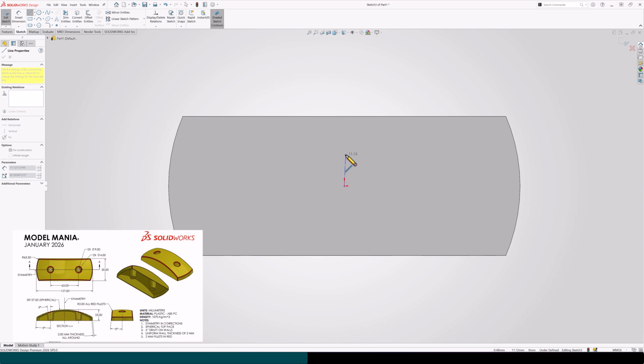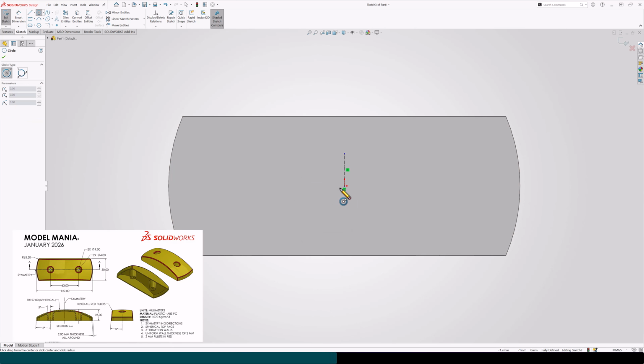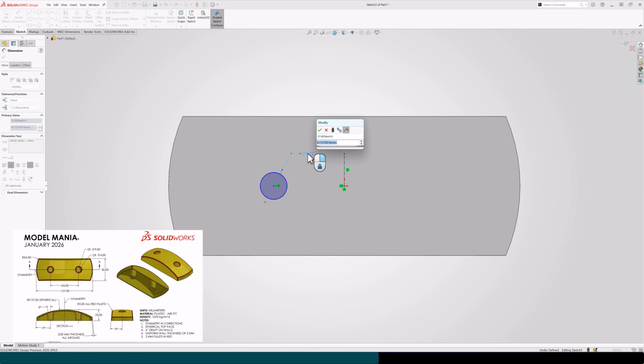I'm going to get started with my midpoint or center line here, vertical again. Click to place my circle, not at the origin. It's going to be over to the side horizontally. Click to place, and then the relationship here to define that that is horizontal. Make sure it's sized properly at 9 millimeters. So click into place that.